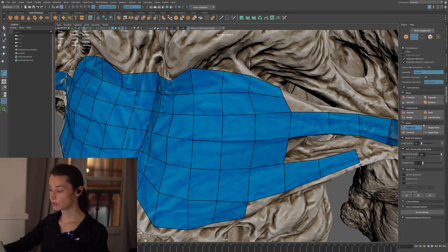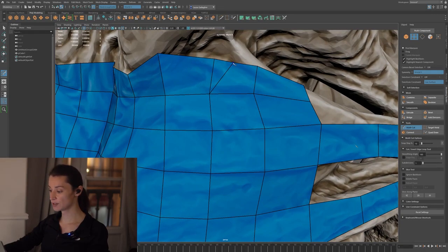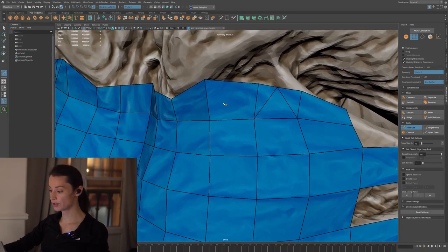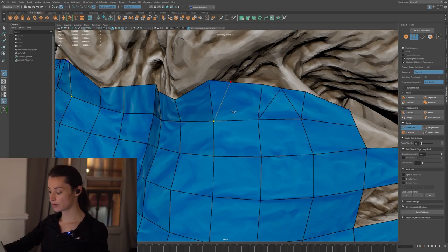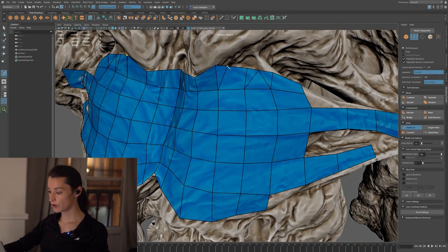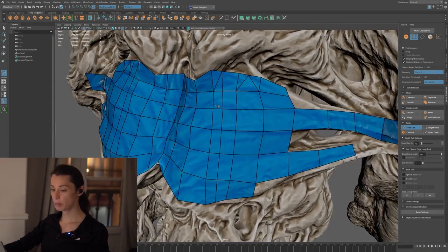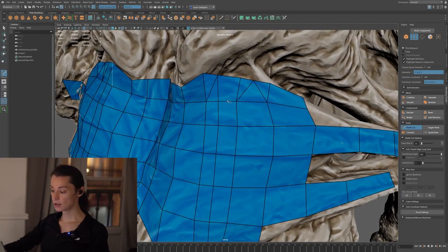And once you're in that mode, you're not technically in Quadra anymore, but the two of those really work very well together. This is a mode now where you can simply click on different places, as you can see, and simply add a bunch of vertices there. So I could add another cut like this if I wanted to. I could add another cut here. I could cut across bigger surfaces, of course, if I wanted to add a full edge loop like this that goes from top to the bottom. So multi-cut, very, very useful the more that you want to simply cut through a mesh, of course.